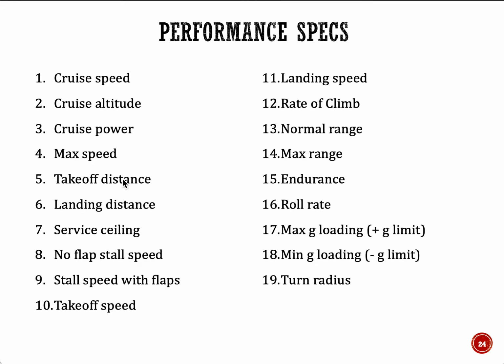Right? There's a lot of performance specs that you may need to collect data on, but not all of them are as important as each other, because it really depends on what type of aircraft you're designing. For example, for a commercial airliner, roll rate may not be that important, but for a fighter, roll rate is very important, right? So you got to make sure to collect that data, okay?